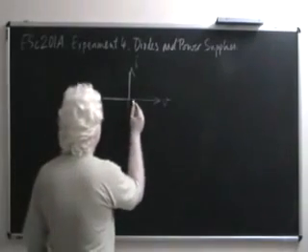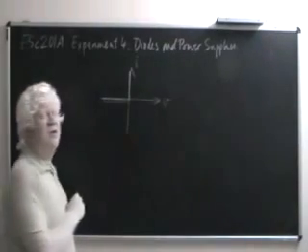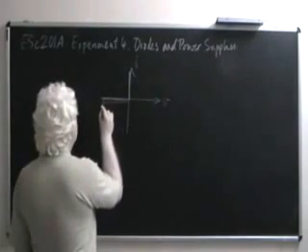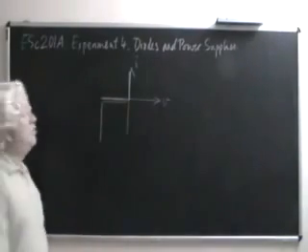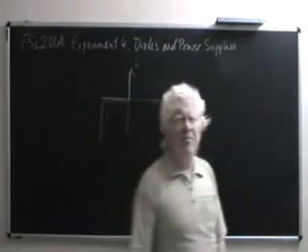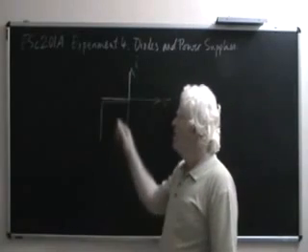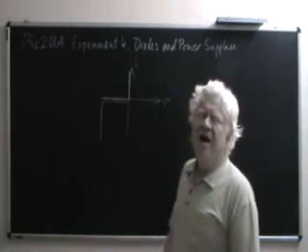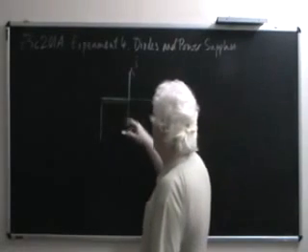So let's look at the reverse characteristic first. Something of this kind, until it breaks down. And the breakdown phenomenon would look like this. So you see, when reverse voltages are applied, there is a very minor current. In fact, the graph which we are drawing makes no claim to be proportionate. It's only indicative. The reverse currents are of the orders of nanoamps or microamperes, whereas the forward currents are easily in the order of milliamperes, maybe even amperes. So this is up to this point.